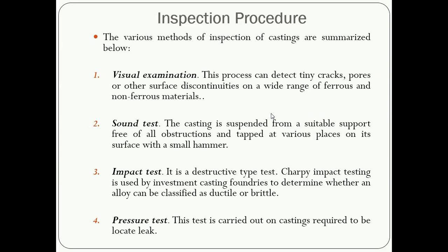If that casting has big voids inside, then you will observe a different sound. And if the casting is completely solid from inside, you will observe a different sound. From the judgment of the two sounds you can easily say whether this casting is solid or has wide spaces. That is the sound test.